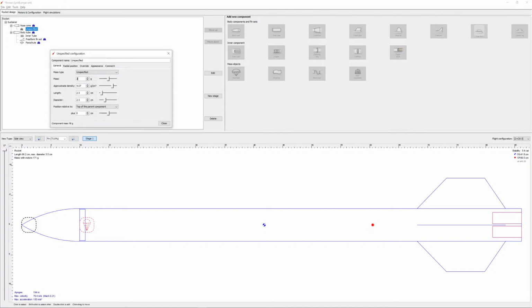So we're going to make that maybe 20 now and see what that does. You can see even that is 1.83 cal, so it doesn't even need to be quite that much. So maybe we'll bring it down to 10 and maybe even 5 after that. Yeah, so this is a stability of 1.15 cal, and you can see the center of propulsion isn't even exactly higher than the center of gravity, but you want it to be close to it.